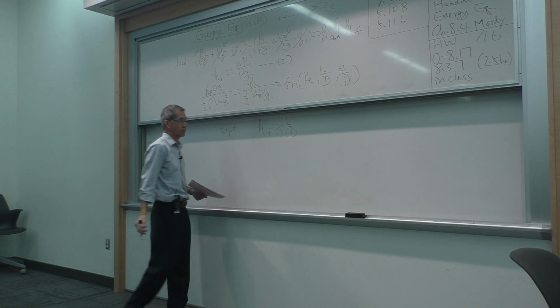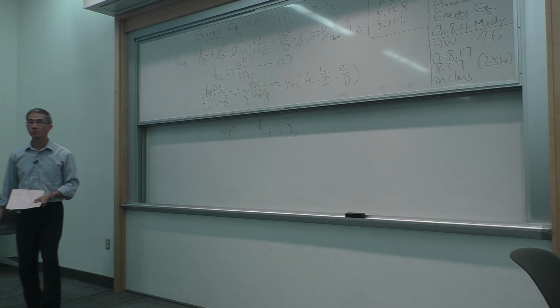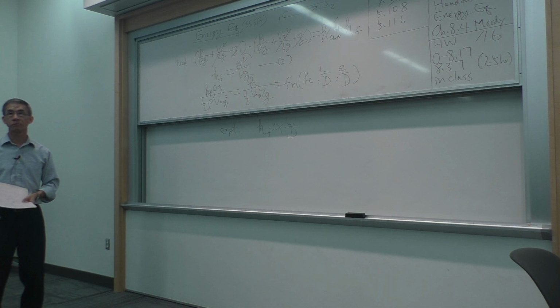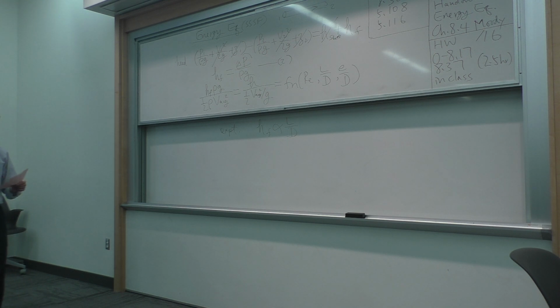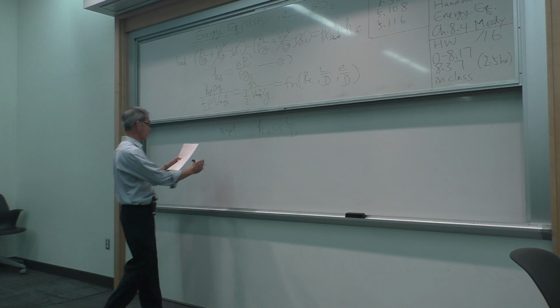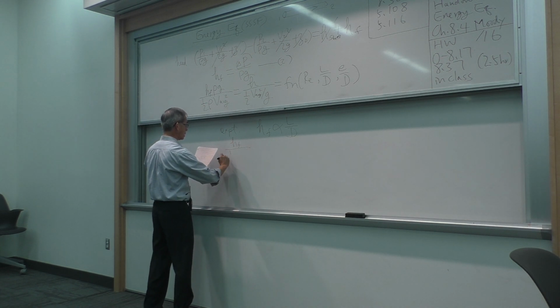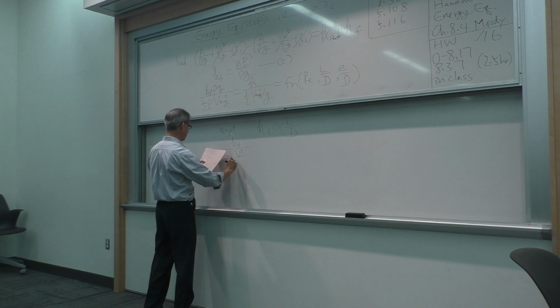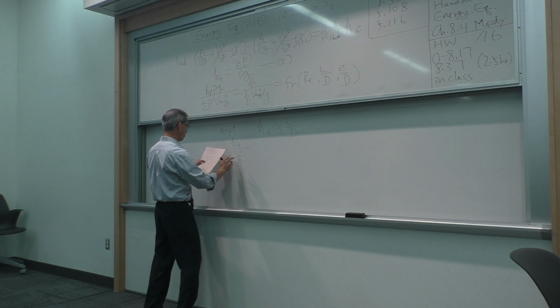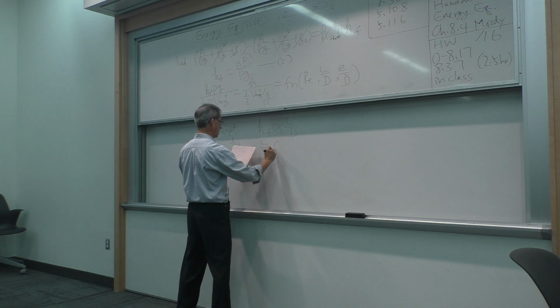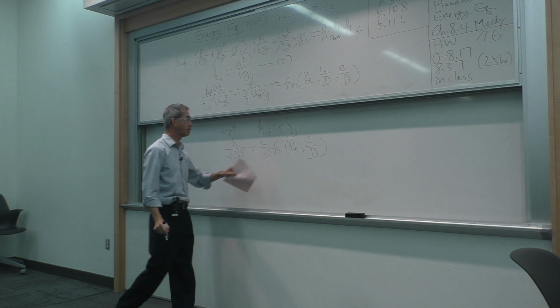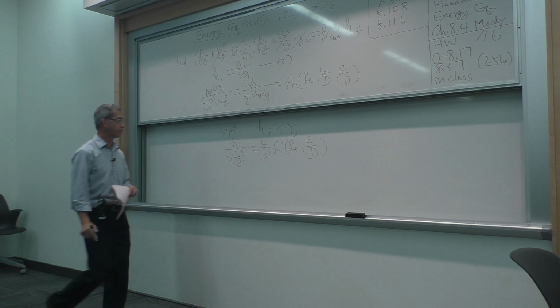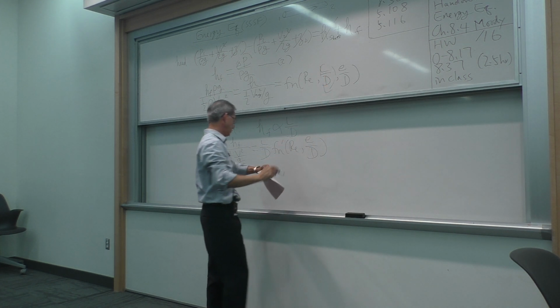Experimentally, he showed that, and it's kind of intuitive, the amount of frictional head loss is directly proportional to the length. The longer the pipe, the more losses, directly proportional. And inversely proportional to diameter: the smaller the diameter, the more frictional head loss. And from that observation, which sounds pretty simple, and with further algebraic manipulation, I can now factor out the dependency of L over D from my equation.